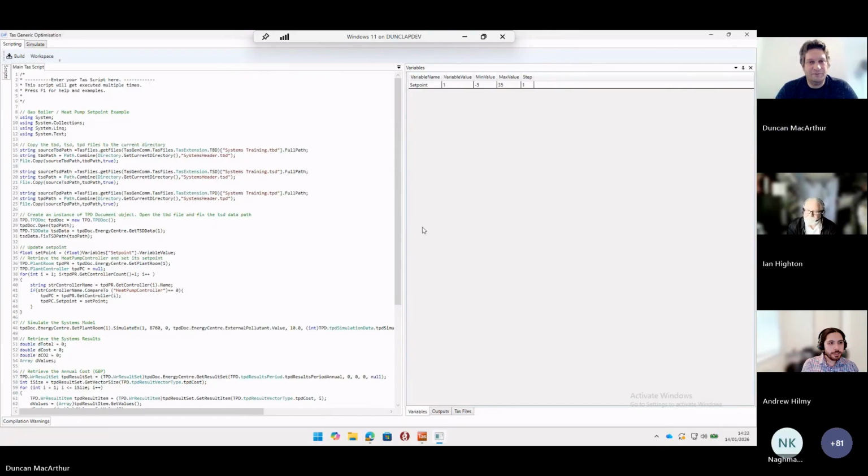And based on that set point, we'll have a consumption, and then each fuel source has a different tariff associated with that consumption, and then it will calculate the cost, and that's the graph that we're getting results from. Okay, so this is the optimal temperature to minimize cost, and the temperature is where you're switching between heat pump and boiler. Exactly, yeah.